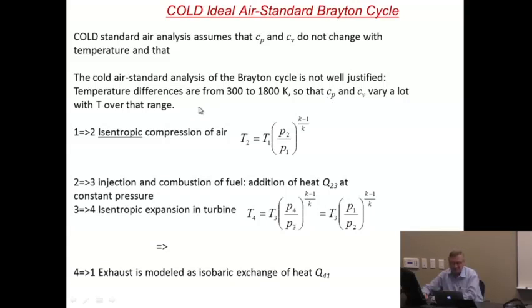They are. So this is an approximation, but it will greatly simplify the equations because now we can say that for the isentropic compression of air, T2 is T1 (P2 over P1) to the power (K minus 1) over K. We have derived this when we looked at isentropic transformation in chapter 6. And the same, T4 is T3 (P4 over P3), which is of course (P1 over P2), to the power (K minus 1) over K. So these equations are very, very much simpler than the equations where we had to look up the relative pressures. They're not terribly accurate, but we will use them for a quick and convenient analysis.